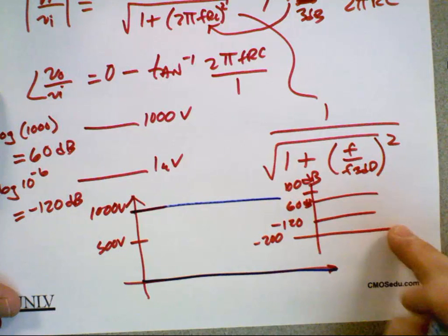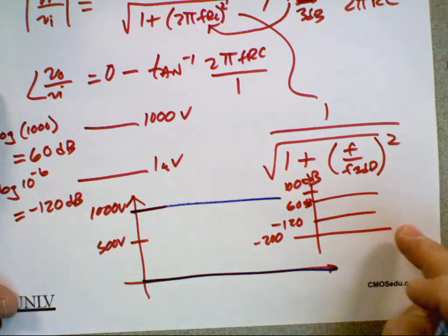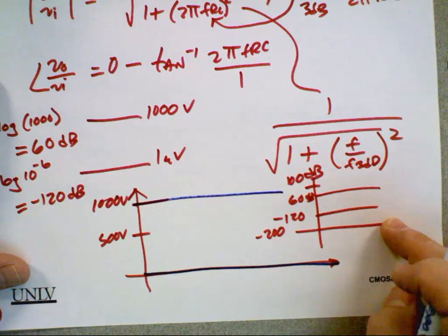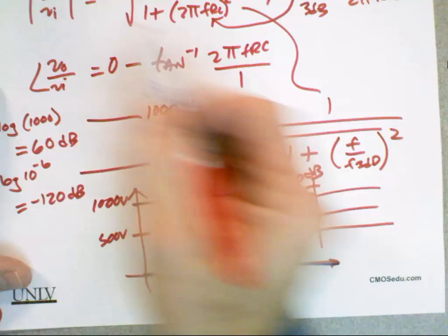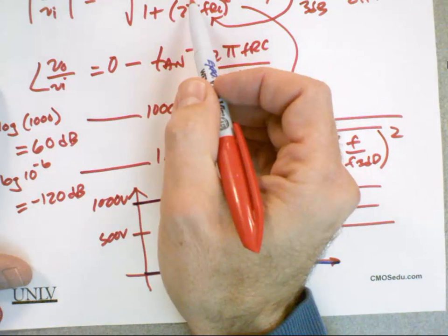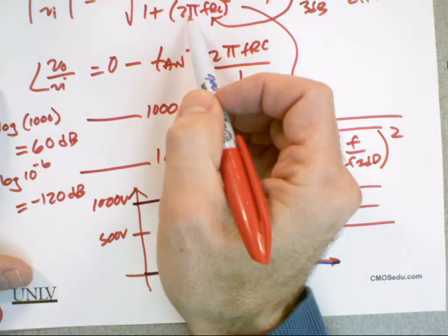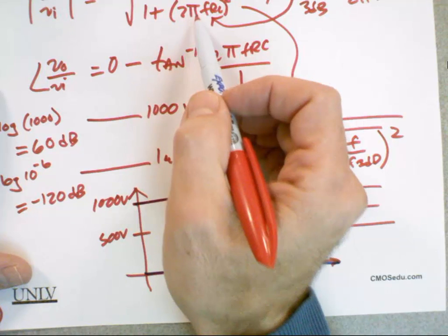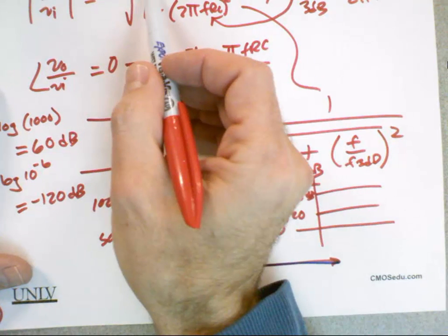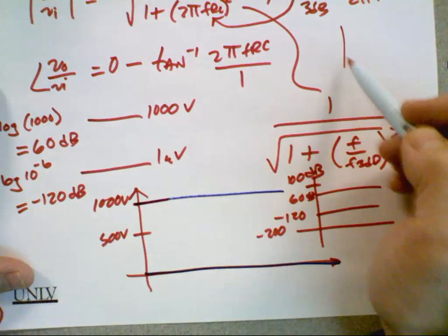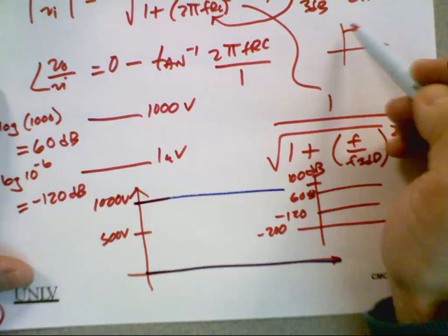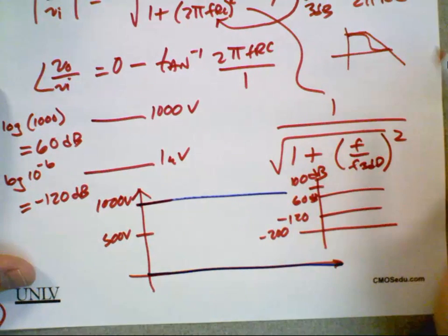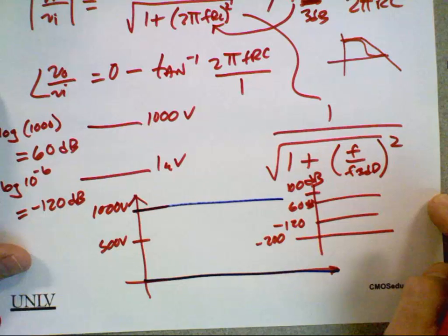Does everybody follow that? Okay, so when we talk about dB and we're doing all these Bode responses, when this f starts to get big, drives this term to what? As f gets really big. 0. Well, it's going to get really, really small, but if I want to compare it to 1, it's hard to do it on a linear plot. If I plot it linearly, it looks like this. If I plot it with a dB plot, we're going to see it looks like this, and I can go down to really tiny values and still see what the value is at a specific frequency.